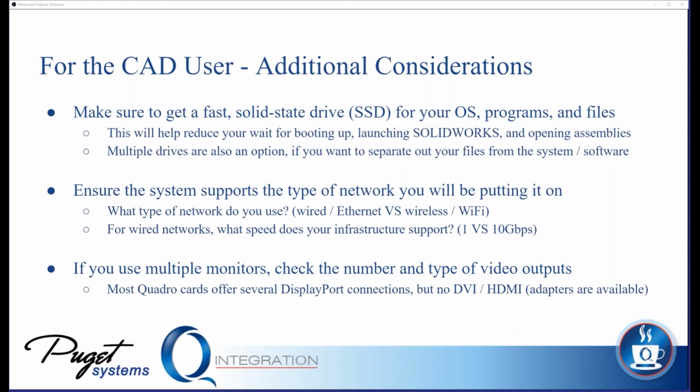And then if you're using multiple monitors, which I do at least at work. At home, I only have one, but at work, I've got a couple. You want to make sure that you've got the right number and type of video outputs from the card in the system. These days, if you're going with a Quadro card for SolidWorks certification support, most of those only have DisplayPort outputs, which is a newer type of connection, and most newer monitors have that. But if you're reusing older monitors, you're going to want to take a look at what inputs they support, and you might need to pick up some additional adapters from DisplayPort to DVI or HDMI.